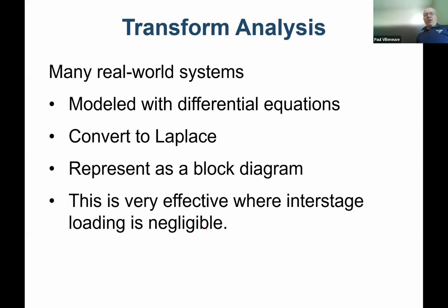All right. So almost all real world systems, if they can vary in the time domain, are going to be modeled with differential equations, right? Because everything's got some capacitance or inductance or something that represents that. And we'll see an example towards the end of the chapter where we can actually model a tank as a capacitor. Because we have differential equations, we have more complicated math to do to get results. But we have this new fancy tool. So let's go ahead and convert everything to the Laplace domain before we do any of our circuit analysis.